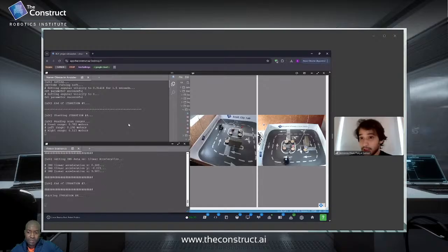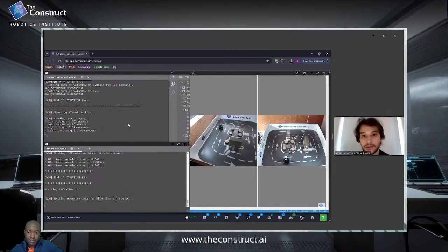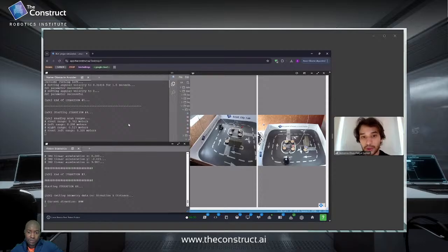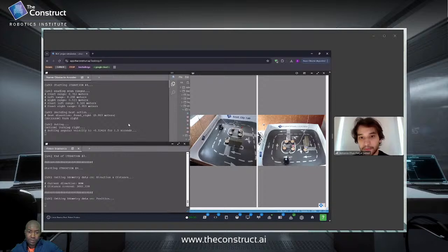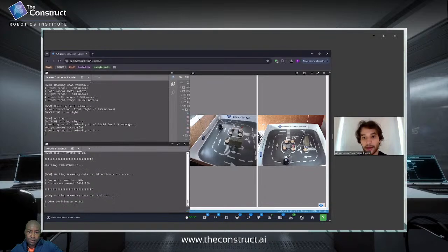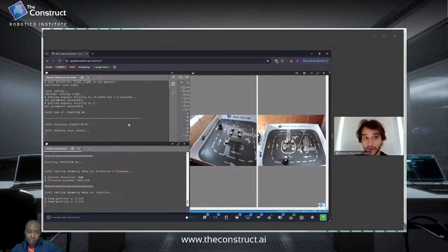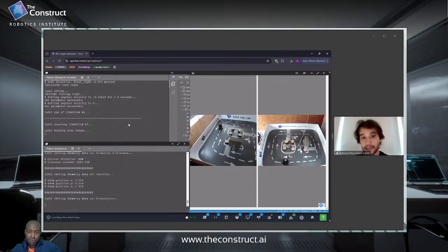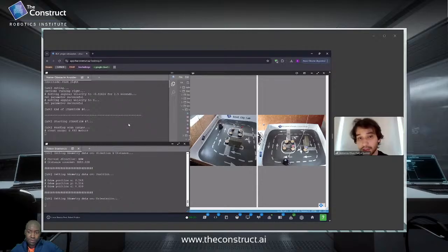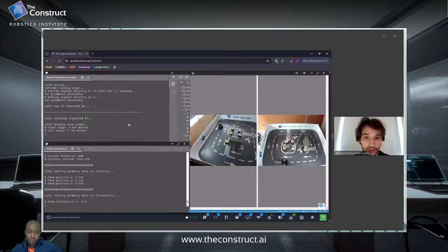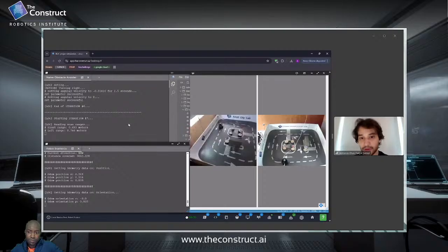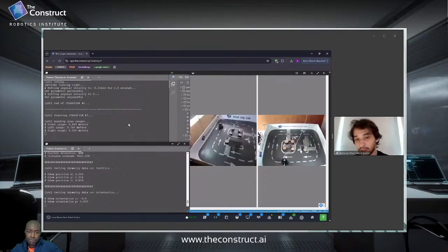I have actually tried to implement some changes to this, but it was extremely hard to implement. What I tried to do was add a new clause detecting front left and front right, and passing to the action function a different parameter, which would then try to turn the robot only 4 to 5 degrees to the respective direction.